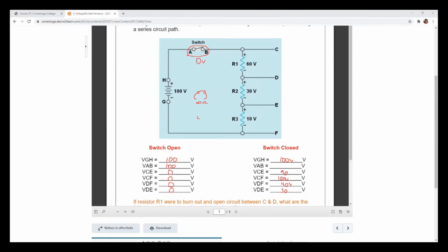And if I have a closed switch and I measure with a meter, how many ohms do I have across a closed switch? Next to nothing, 0 ohms. So what is the potential difference that is required to push current through a 0 ohm component? Nothing. It's pretty much a dead short. With a minimum amount of voltage, current will go through. Kind of make sense?